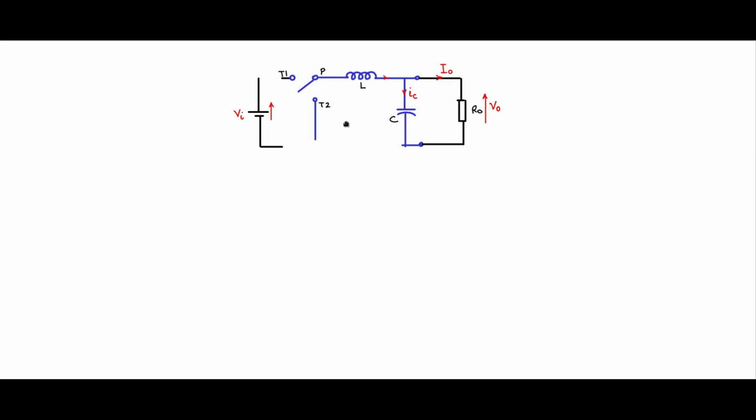So the inductor cannot be on the throw side of the single pole double throw switch. Suppose the inductor was on throw 1 or throw 2, and whenever the pole was not connected to those throws, the current there would be 0, and the inductor current cannot go in a discontinuous way to 0. Therefore, it is also constrained that L has to be connected to the pole.